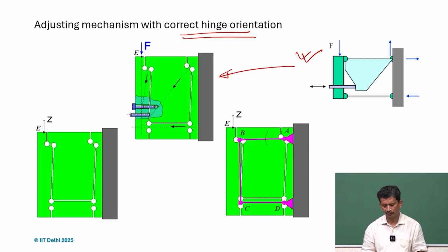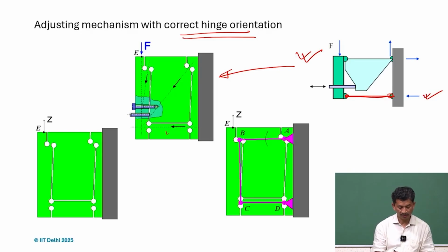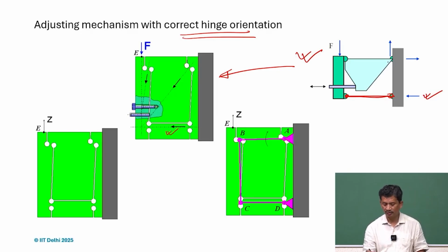So what is required is we have to do the force equilibrium. So write the forces. What we realize is this is the two force member. If we take this, the direction is known. In that case, under equilibrium, there will be only this force, right? Either in tension or compression. So that force is known. This part is the three force member. So one will be at this part, and then one here, one at the support hinge, and one external force also acting here.